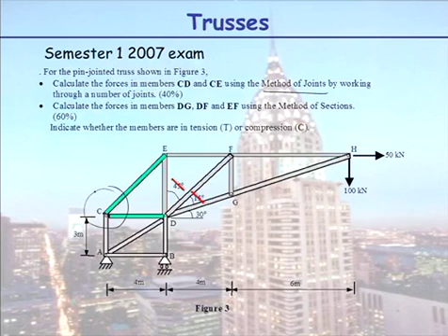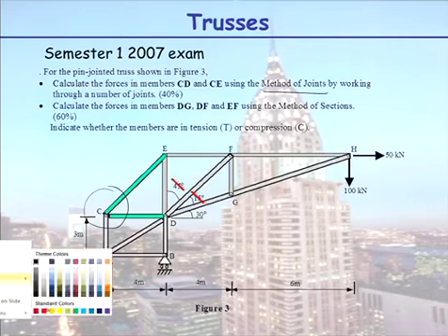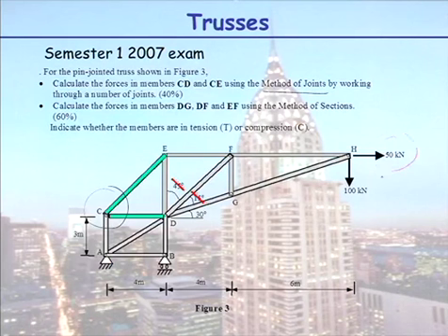Now, working your way through, you're better off working your way through from A and B rather than H, because if you work through from H, you'd have to look at joint H and then you'd have to go to G and then F and then E. Whereas if you work the other way, you would only have to work through joint B, A and C. So, in order to start at joints A and B, you need your reactions, and people went wrong, once again, calculating their reactions because they, once again, made the error of not considering the moment effect of a horizontal force.